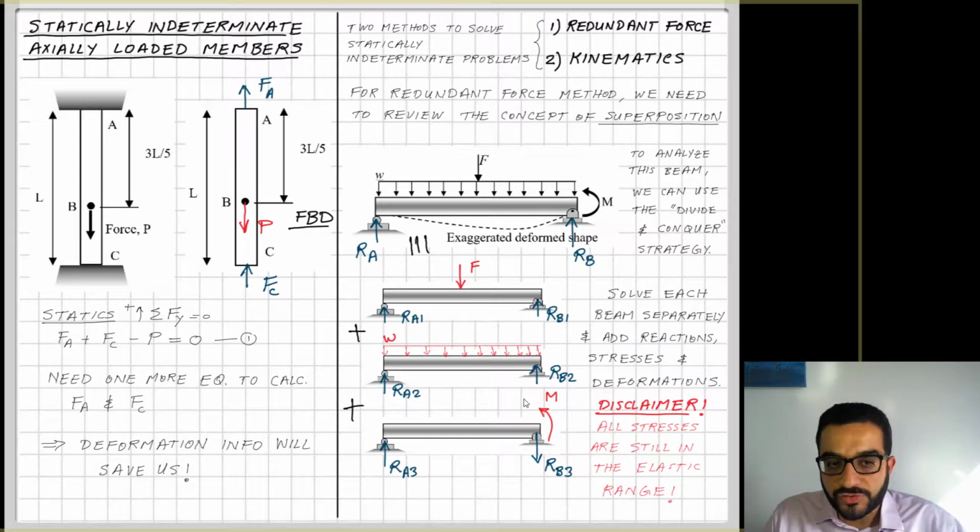So we have to be very careful that the behavior of this beam is always within the proportional limit, because in the proportional or elastic region, the behavior is linear. So I can add the values under the assumption of linear behavior. This addition will bring you to the original load case and its impact on the beam.